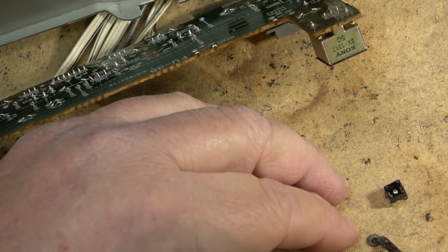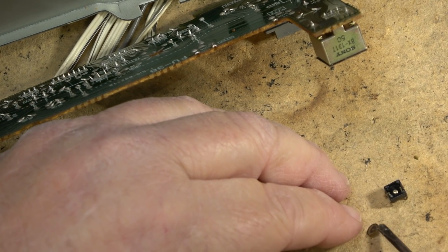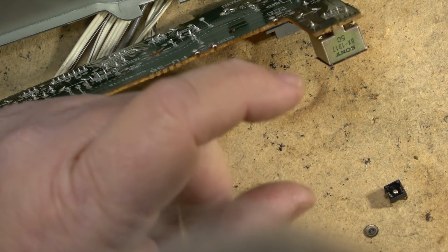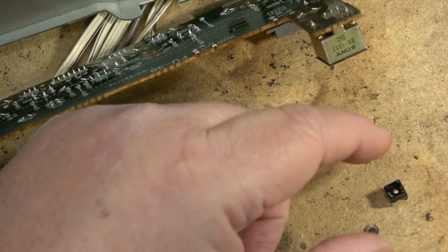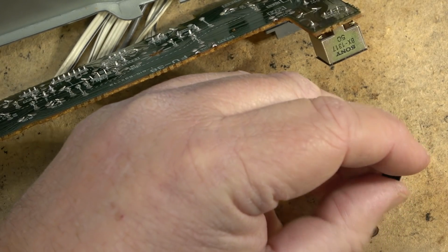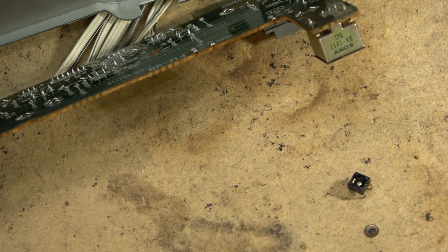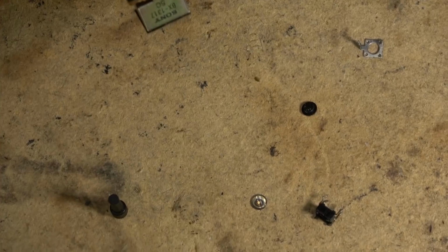This is made out of, I think, silver plating. But this is where our problem is. We have resistance building up on here. So I'm going to clean these contacts a bit. I'll put a bit of DeoxIT on there, polish this up, put the switch pad together, and this should go into rewind.